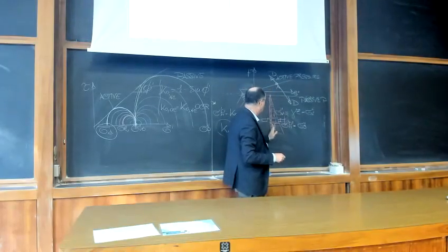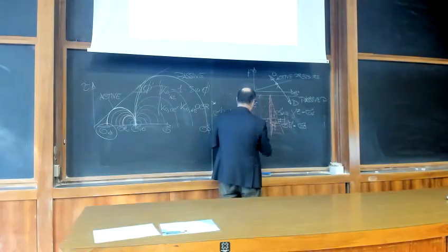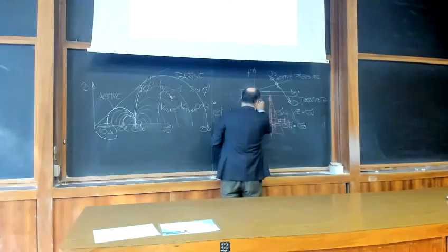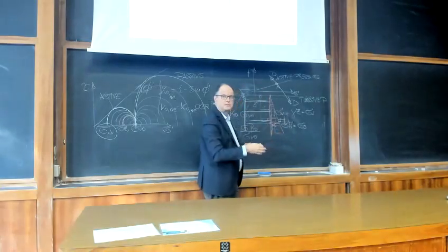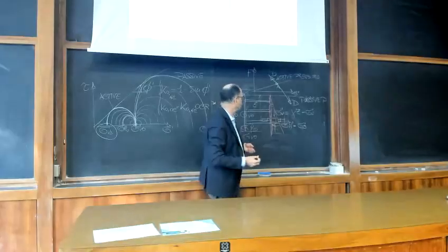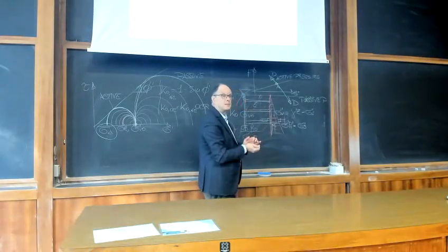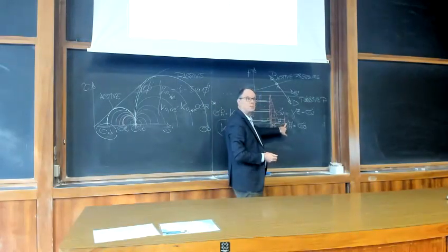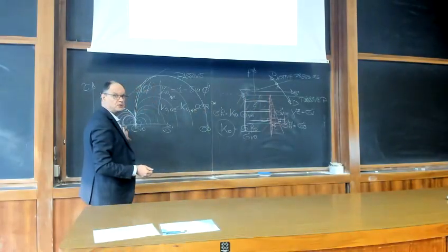There are possible walls in which you have, let's say, an excavation like that, and you have some structural elements like that. So this is a very rigid structure. You will see when we design retaining structures that this is totally prevented from moving. In that case, you cannot consider the minimum, but you have to consider the initial stress state.